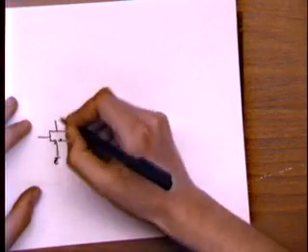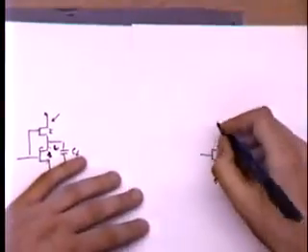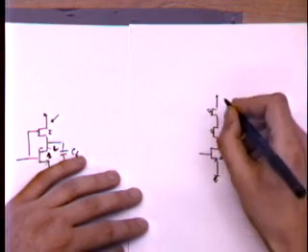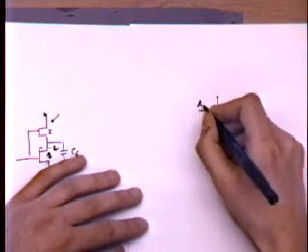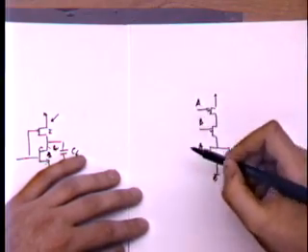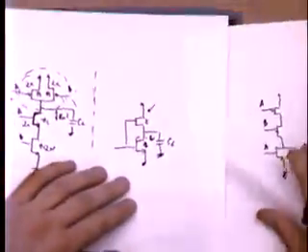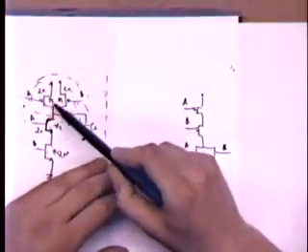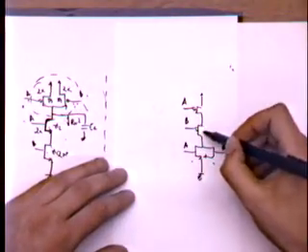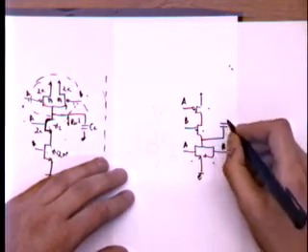So if you look at this NOR gate and you compare to the previous NAND, you will see that this NOR is actually the dual of the NAND gate. So in other words, the NAND gate has two series NMOS and two parallel PMOS devices. And the NOR gate has two parallel NMOS and two series PMOS devices. And the output is taken here now. So this is CL.